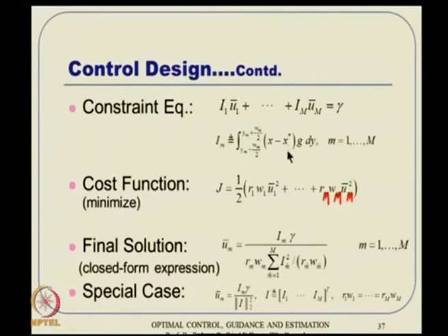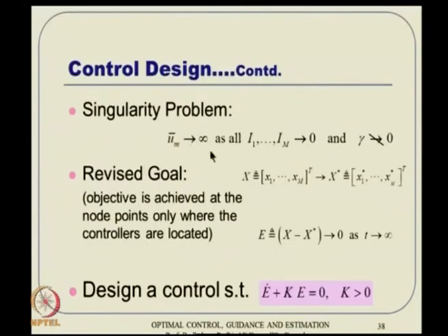So, at that point of time we tell, okay, if the objective is met, then why getting ambitious and telling that, okay, through this control actuation I will be able to control in other domain also. It may not happen actually, because wherever control is actually located, there I should see some error at least, okay. If nowhere else I see an error, then it becomes some sort of an observability problem and error is not there. So, control remains a kind of silent actually, because it thinks, okay, the objective is met sort of thing actually, okay. And if you really want to control it through the errors in the other domain, because the errors are 0 here, that means the control effectiveness is 0 at that point in space. So, every control starts blowing up actually, it goes to infinity actually, okay. That is the physical reason for that.